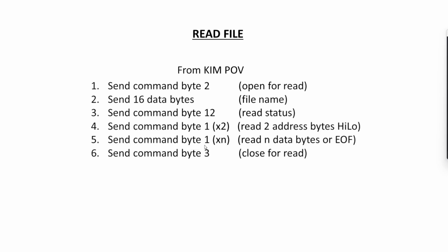So it's going to read 1 byte at a time for however many it wants. There is a file length built into the data header, how long it is. And when you reach the end of it, the solid state drive will actually send an end of file. If not, you just read 1 byte at a time and put it wherever you want it. If you know how long it is, then that's fine. If not, you just wait until you get end of file and know you're finished. So it then just sends command byte 3, which is close it.